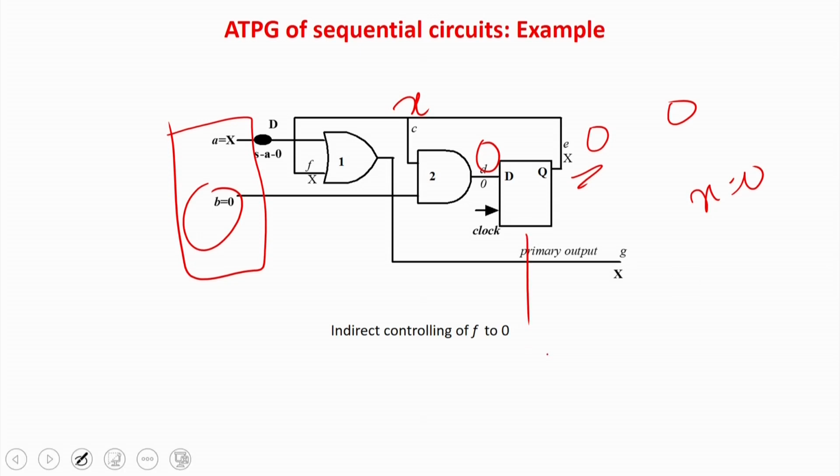Basically you can directly make the reset line equal to 1, so that it directly becomes 0 and you can do the job. And the advantage here is, even if there are 200, 300 flip flops, all the set and reset lines will be controlled separately and they can be brought to their required values. So you require just one clock period, or just one test pattern, to set and reset all the flip flops as required by the test pattern.